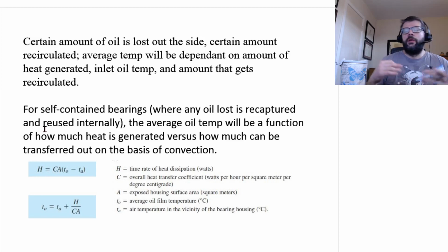Of course, doing so takes effort and increases your equipment and operating costs, but so be it. But for self-contained bearings, the oil that leaks at the side is recaptured and recirculated internally, and basically all the heat that's generated needs to go somewhere, and the oil itself isn't carrying it off to some heat exchanger or what have you. So you're relying only upon convection to get stuff out of there.